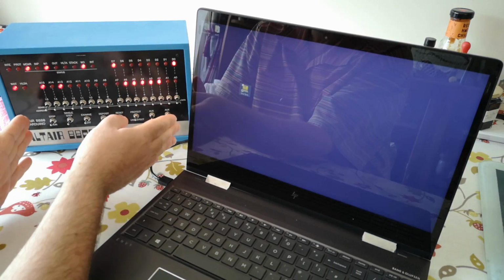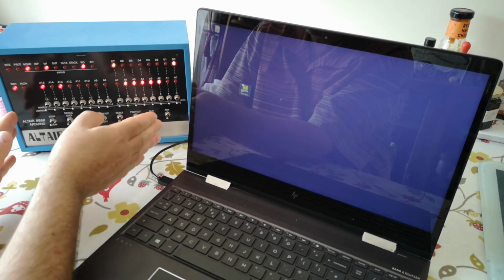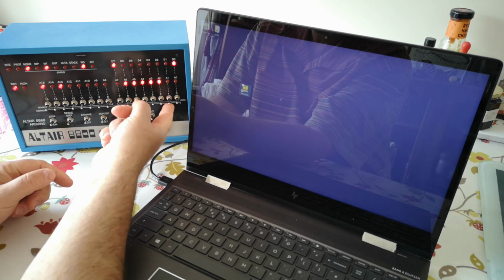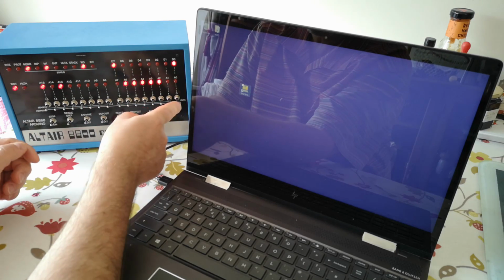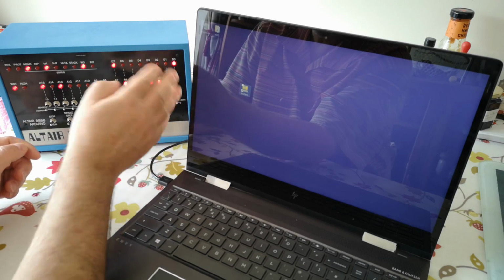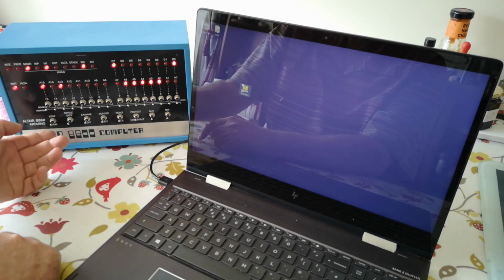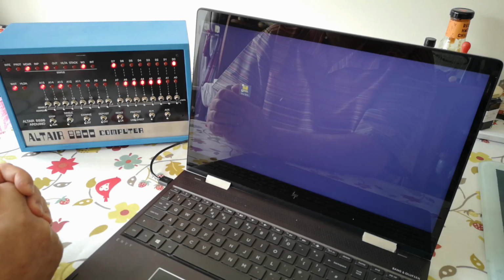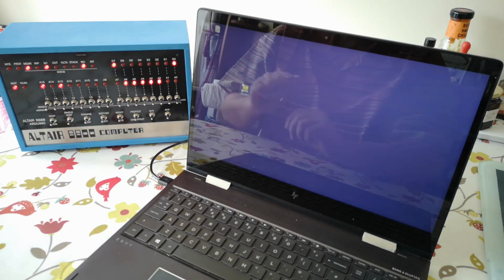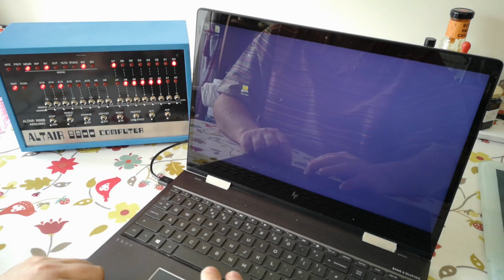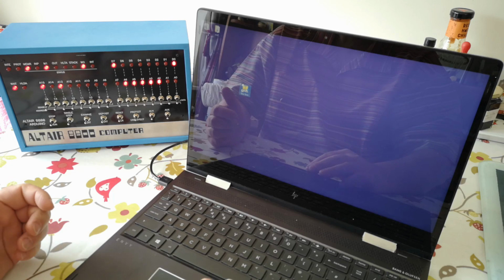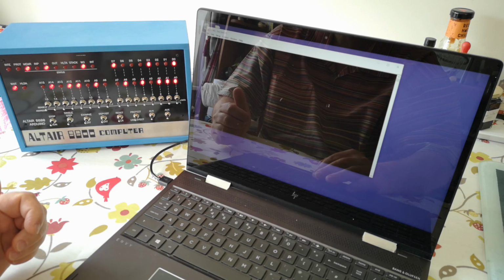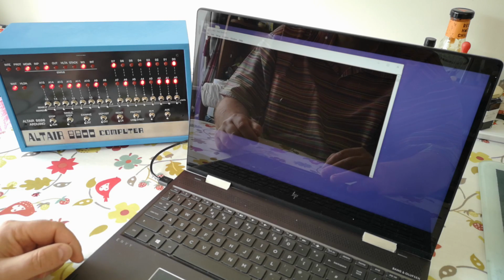Now you can program this computer and use it entirely standalone by using the switches on here to select memory locations and to push data directly into memory, and then you can run and stop programs using the control switches down the bottom here. It's really hard work doing that, so very quickly people found other ways to do it, and so we can connect this to a terminal,